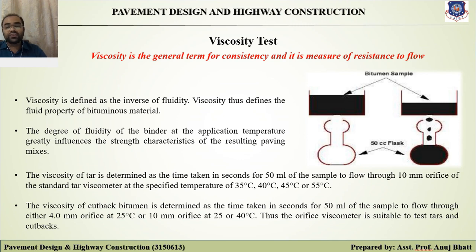High or low viscosity during mixing or compaction has been observed to result in lower stability values. There is an optimum value of viscosity for each aggregate gradation of the mix and the bitumen grade.